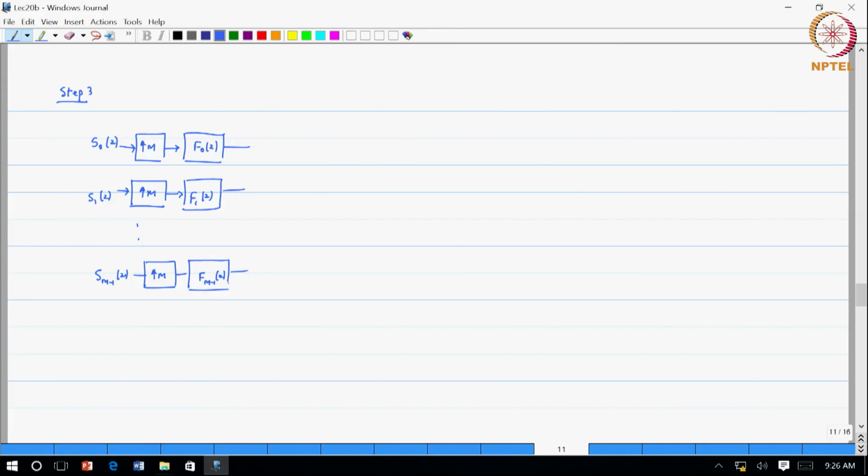In most transmultiplexers, the summation is not at the top, it is shown at the bottom. Okay, do not get confused, it is exactly the same thing, it does not matter at all, but there is a reason for this. Anytime a synthesis is happening, you show that all the signals come and get collected at the bottom. It is just a convention. So, instead of keeping the summation at the top, this is what is going to be fed to your channel, whatever your channel is. In this case, it will be a mobile fading channel to which you will transmit the signal.